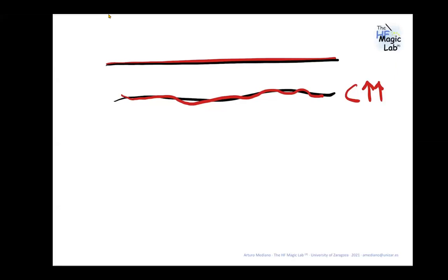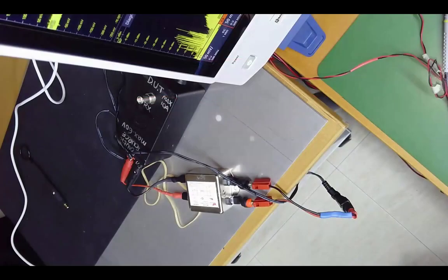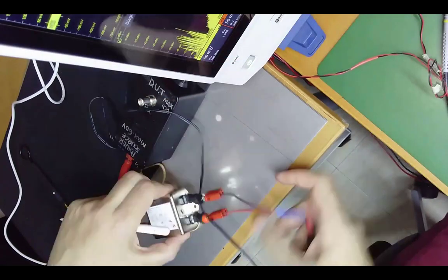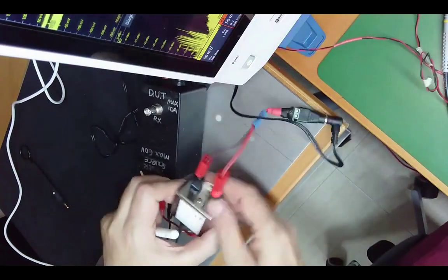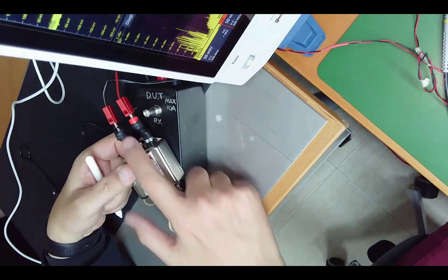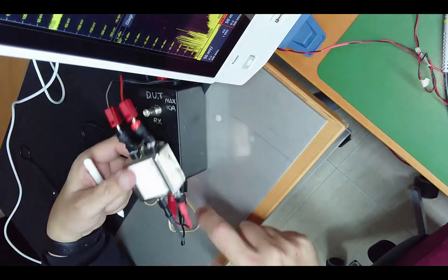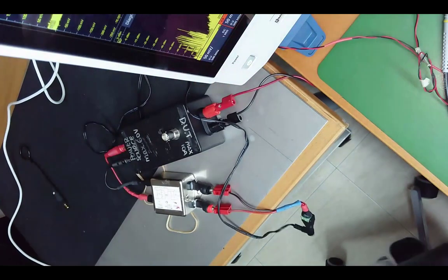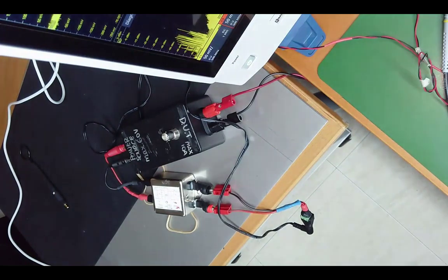This is what I am doing here in my demo. Let me show you with the camera. In my demo, my 20 volts goes to the device under test through this filter. This is an AC filter. So DC is going through, and I am filtering any noise from, I don't know, 150 kilohertz to some megahertz, which creates a quiet power supply for me, no?